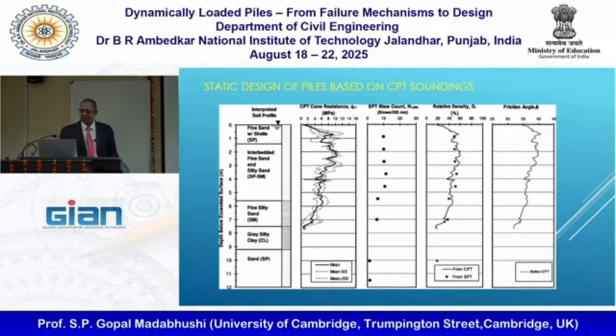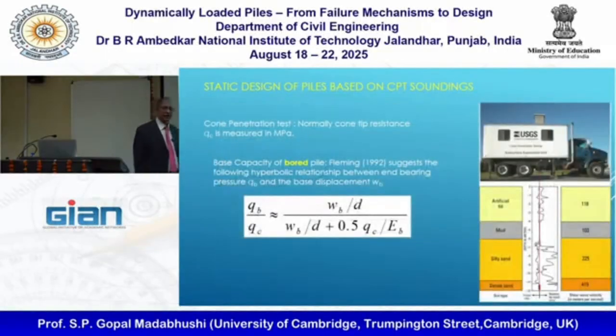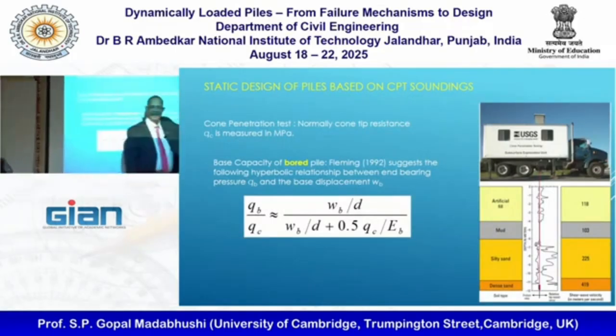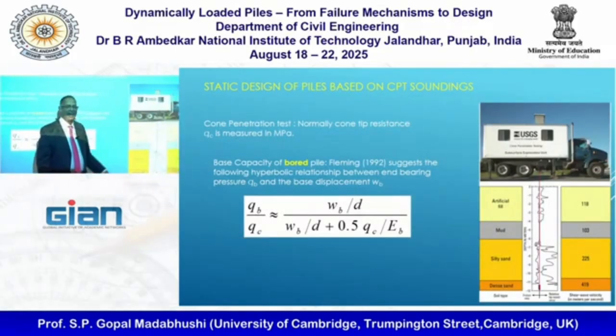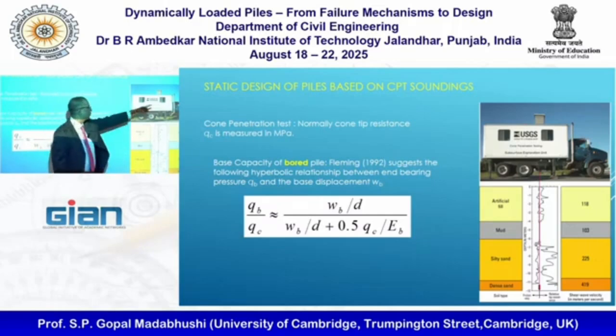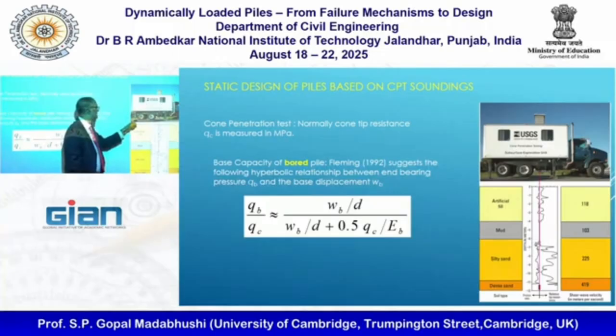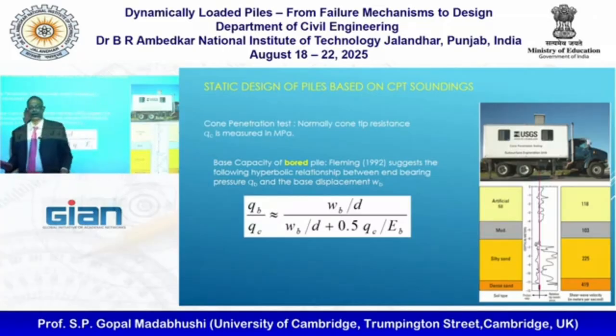So, this is a typical CPT truck. I believe Aniruddhan or somebody in Chennai has a truck like this, and there are a few others who can buy them, and clearly there are not enough of them. That's why we are still struggling with SPTs. But you use the truck as your reaction, and you push the rod in between. So you can see the whole weight of the truck is your reaction load, and you push the rod inside, and you get your QC values directly from that.